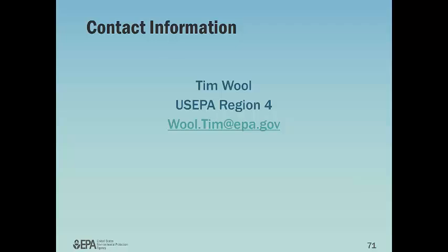Yep. A question about kind of metals and chlorides specifically. Do those kind of concentrations affect DO in a stream or lake? Well, chlorides definitely affect the saturation point. Metals will affect the available oxygen because some of the metals, like iron and such, will remove oxygen, dissolved oxygen, from the water column to adhere to the iron. So they do have an effect for sure.